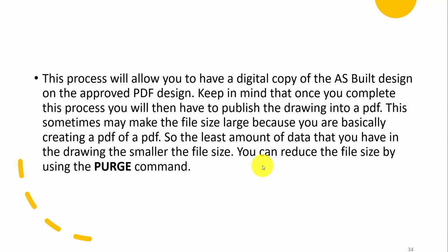Now, keep in mind that using the Purge command, you can purge basically anything out of the drawing. Layers, blocks, line types, all the different styles. So if you're completely done with this design and you're ready to just put it away, you can do that purge and just purge everything out. And then that way it'll reduce that file size. So I'll go ahead and walk you through the steps in Civil 3D to conclude this presentation.